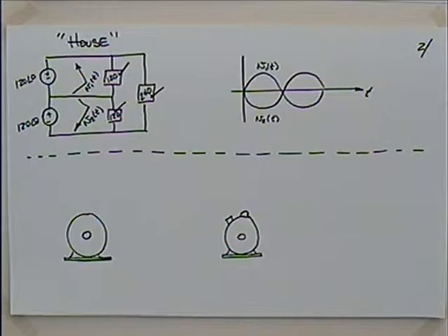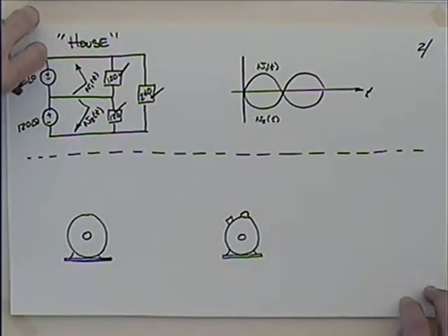So you definitely don't have three-phase in your house. People get burnt on this all the time because they'll go to some industrial sale and they'll buy a really nice table saw and it's a super deal, and they get it home and, oh, it's a three-phase table saw. Okay, so probably not going to work, right? You're going to have to change the motor, or you're going to need a phase converter or something like that.